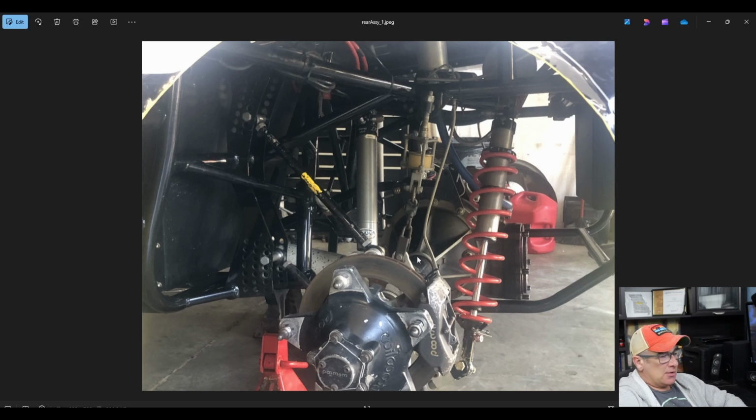And so we are going to completely define the position of all of these elements in this rear suspension. And using all of our outputs from our model, we're going to be able to determine things like birdcage indexing, rear steer, 5th arm position, J-bar angle, spring angle, or how the spring is angled to the chassis. Anything in this rear suspension, you name it, we're going to be able to figure out what it is.